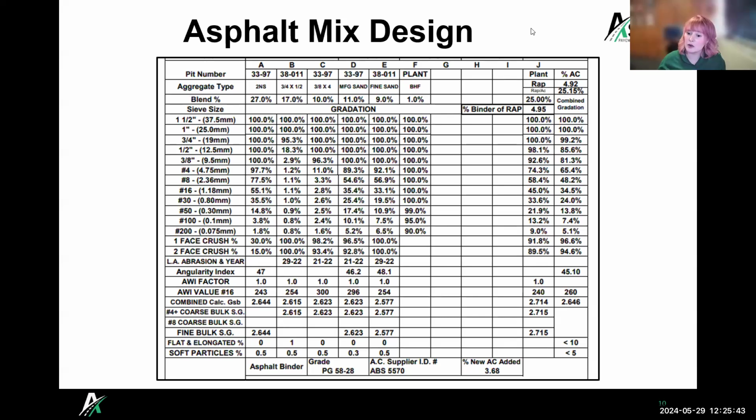Good. So this person had the question, why not just design for 3% air content from the start instead of designing for 3 and then regressing, or designing for 4 and regressing to 3? The problem with designing right at 3% is you can close up some of those air voids with something other than liquid asphalt. So when this change came on the MDOT side of things, we wanted to find a way to get more liquid asphalt in the mix because we were having durability issues with the Superpave mixes.